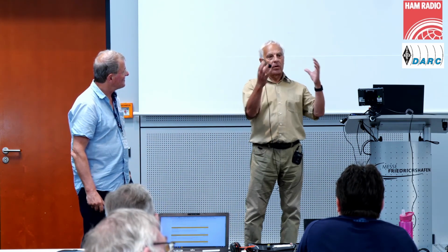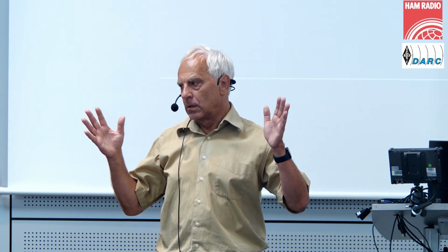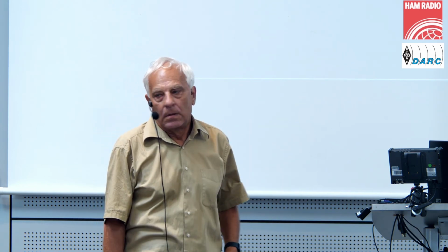Actually, in the normal PLL, I have 40 hertz bandwidth before the phase detector. The low-pass filter has a 20 hertz cutoff frequency. And in the normal PLL, I have around a 1,250 decimation factor. So this FLL is a little bit slower, but it still works. And the filter length in the normal PLL is 5,000. Okay, thank you. That was the first question.